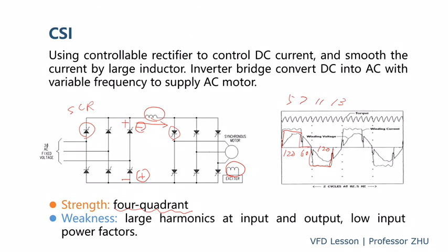And on the opposite side, the waveform is also not good. So this current will produce extra heating on the motor. And the torque pulsation will generate a resonance problem on the mechanical equipment.